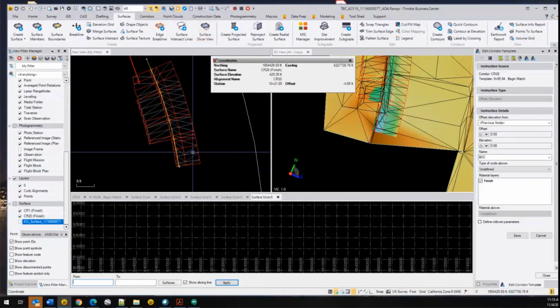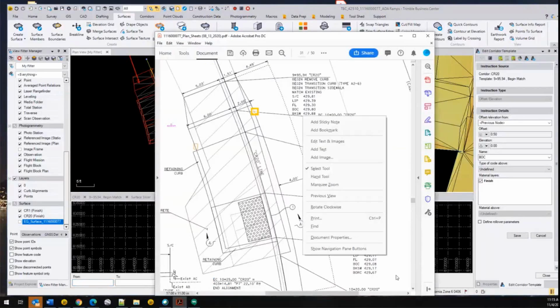And then you're going to build that curb per the detail, and they're really just going to match what's there at that first station. If it's the same type of curb at all, sometimes at tops of ramps, we're going to have the AC dike or something. They're just going to make it work. It's on the upstation or lower part of this where we're matching, I believe, an AC curb here.